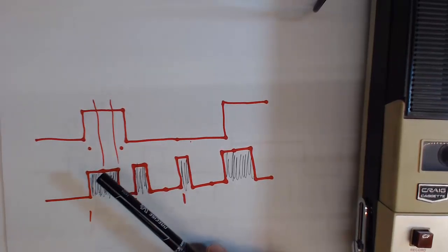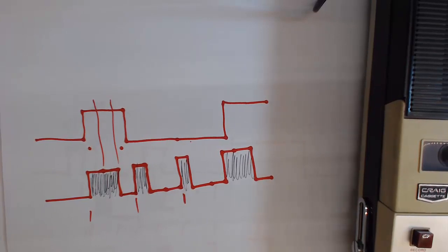Then we have routines for writing data out to the tape. And so you can tell already we're bit banging this, and writing to the tape is extremely easy. We just pick a counter, and we just pick a frequency that we're going to output. And if that is a logic 1, we output for 2/3 of some time period the logic 1 or the burst, and then we wait for 1/3 for the stop bit. If that bit that we're sending out to the tape is a logic 0, we do our burst for just 1/3 of the time and then pause for 2/3 of the time. So it's really easy to send the data out. Now reading the data back in is fairly simple too.